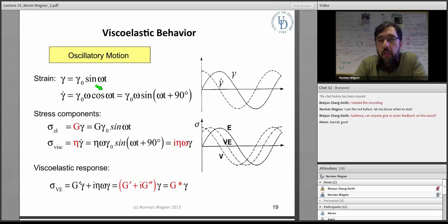We will also talk briefly about viscoelastic measurements, where we do a deformation that's time dependent. The most common one is to apply a sinusoidal deformation in the strain, which means that the shear rate is a cosine. We can define the stress also as being an in-phase and an out-of-phase component. That's shown here in the diagram. The in-phase component with the strain is the elastic part, or G prime, the elastic modulus, and the out-of-phase component is the loss modulus. So we can get additional information by oscillating the sample and measuring its response.